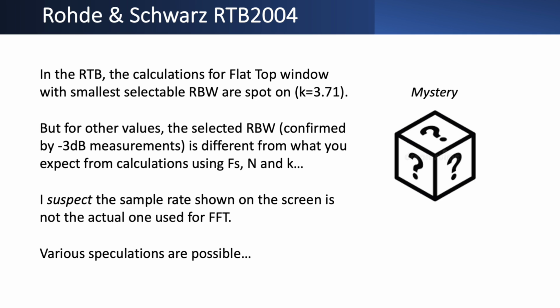Now again, this is all speculation, and whatever they are doing, for me it's like a black box, and we don't get to know what the actual main FFT system parameters are. And this is a bit of an issue, because if we don't know the actual FFT sampling frequency, we also don't get to know the Nyquist bandwidth, which is half of that frequency, and we also don't know whether the settings we've selected are appropriate for the type of input signal that we want to analyze.